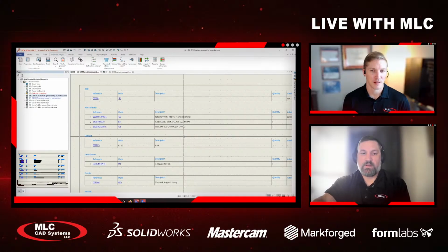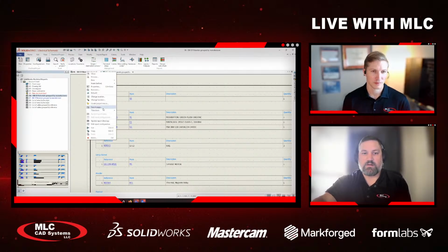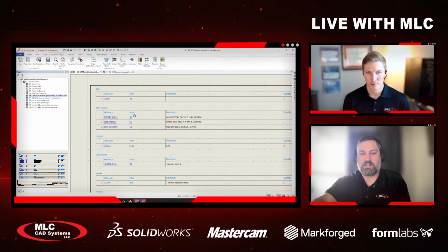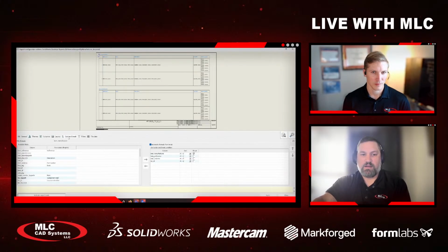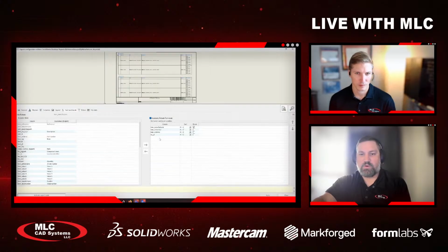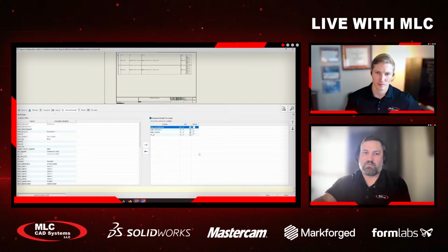Super handy. Now, sometimes people want to list these reports as one big report rather than by manufacturer. So that's another change that we can do. Let's go to the report here. I'm going to say edit report configuration again. This time there's a sort and break tab, and this is where we can specify, you'll see right now it's breaking by the manufacturer. So if I uncheck that, it won't make those big breaks every time it switches manufacturer.